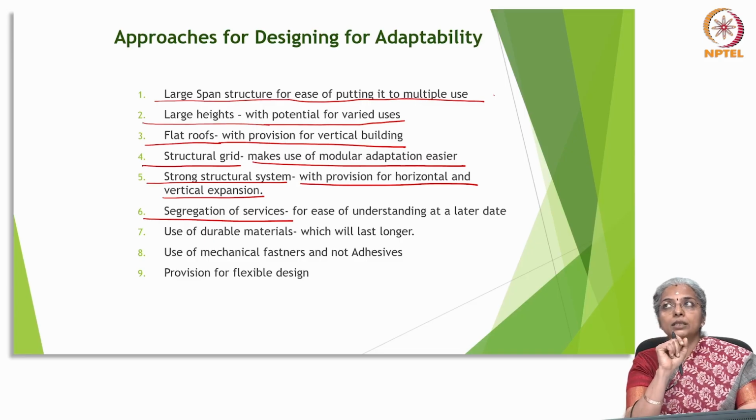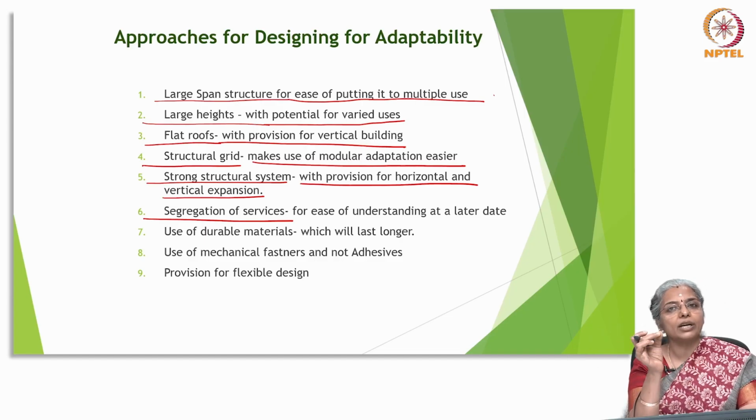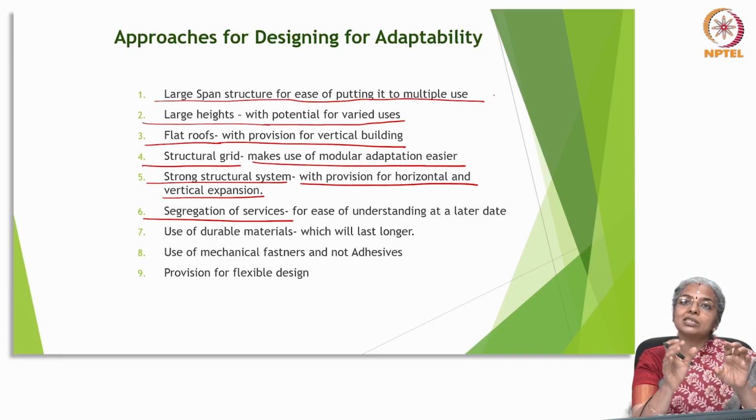Because what happens is, over a period of time, if you start to renovate the bathroom, and there is a small leakage in the existing pipe because of wear and tear, without you knowing, slowly there is moisture seepage inside the wall because of the very small leak. It may be just tiny drops of water seeping out, but over a period of time the moisture in the wall will build up, and moisture is the biggest enemy of any building.